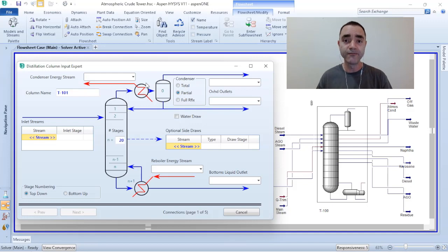So when you have a distillation column with a reboiler and a partial condenser, each one of these units or each one of these sections represents one vapor-liquid stage of equilibrium. And you can verify that because you enter with liquid in the reboiler and you have addition of energy, and you are able to have a stream that is vapor and another stream that is liquid.